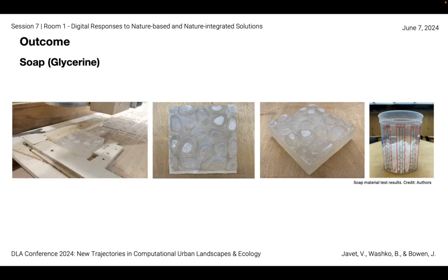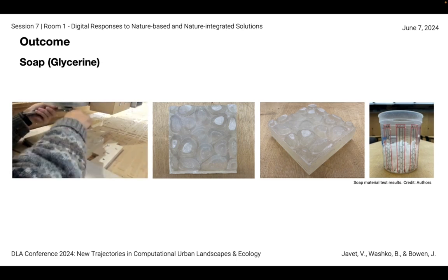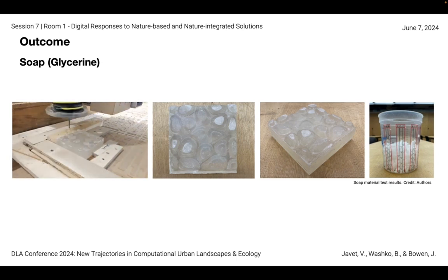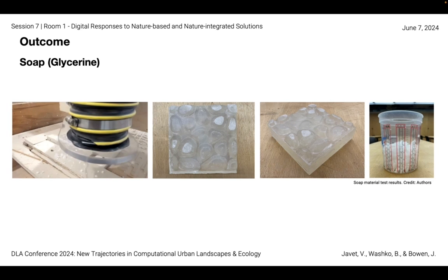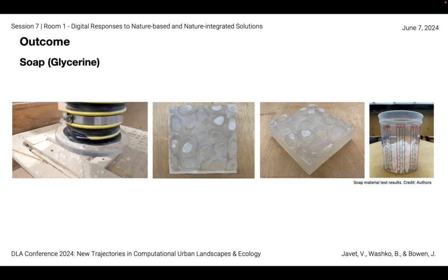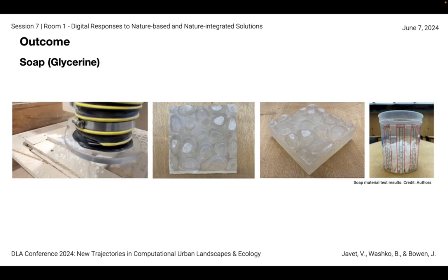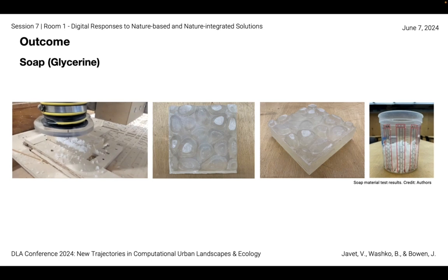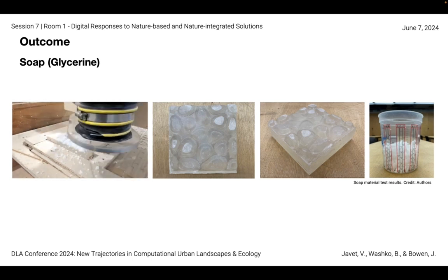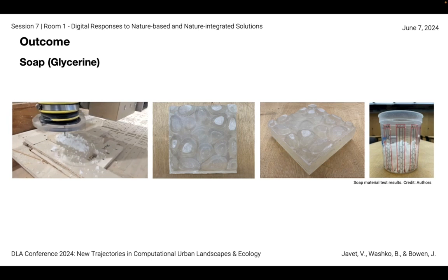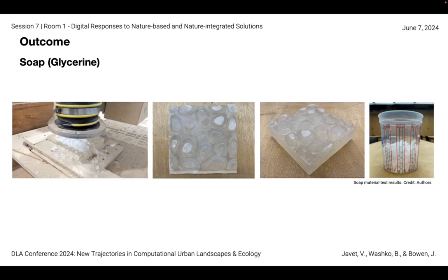Soap provides a compelling opportunity to bridge the accuracy of digital fabrication with the human hand to smooth, sculpt, and rebuild or iterate on the model in an analog manner without needing to further use tools for fabrication. The largest barrier to soap as an alternative material was that slopes over 50% were susceptible to cracking and breaking off of the model due to the vibration of the machining speed, which could be solved by using lower milling speeds for future tests.